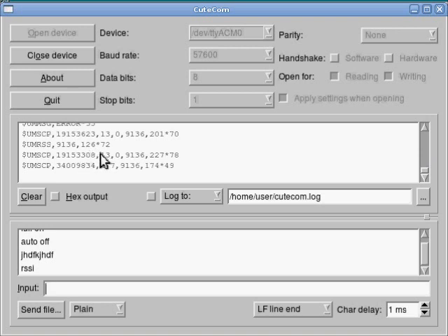So that's fine. That's interesting. We can see that noise floor then for that channel is around 126, and these signals are coming in at 227, 174, way above the noise floor. They're nearby, so that makes sense. If I'd like to, I can change to a different frequency. Let's go someplace where I don't think there's any data. If I go to 903.0, 9030, we should see that the data just stops.